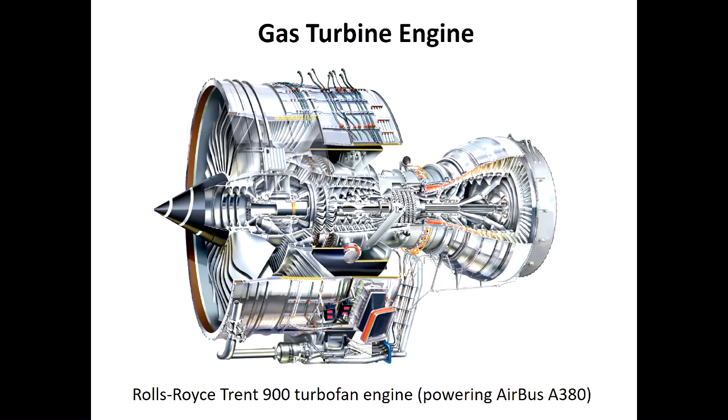If you heard the news, unfortunately they will stop building it in 2020 or 2022, but anyway, there are quite a few still in service today. So this is a huge engine, and if you're looking at the major components here, you have a fan at the front, and then there is a series of rotors and stators as the compressor, with a lot of stuff going on here, and then you're going through.